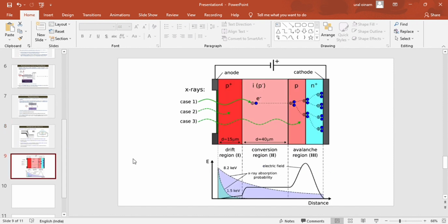And then we have the avalanche photodiode. The concept of the avalanche photodiode is quite similar. In this case, when light falls onto it, there is an avalanche breakdown that happens inside. So what is avalanche breakdown? The electron that is knocked out of its orbit moves inside the photodiode. When it moves inside the semiconductor material, it knocks out other electrons from other atoms.